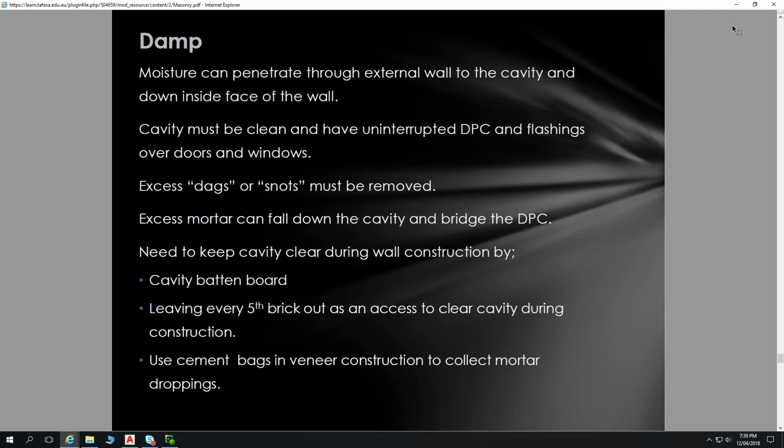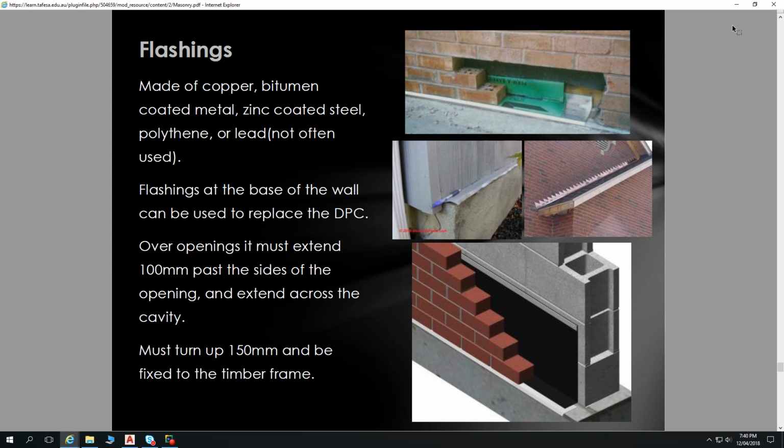Various different ways of doing that: with a board, or with leaving every fifth brick out to access the cavity. Use cement bags. You use old cement bags and pack them in that gap, in that cavity in the wall, to collect all the excess moisture as well. Excess mortar as well.